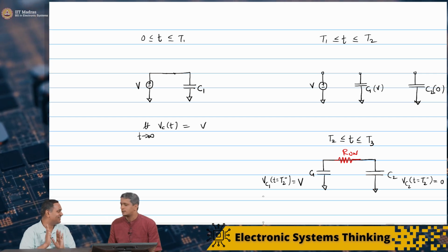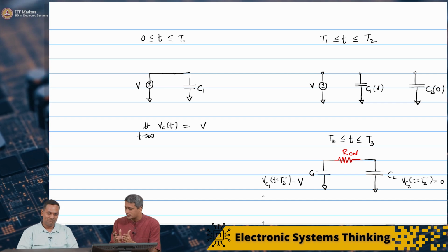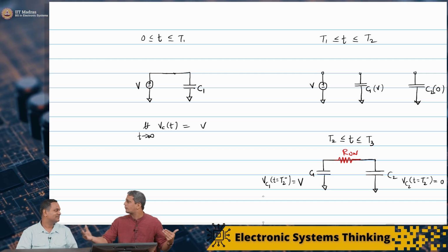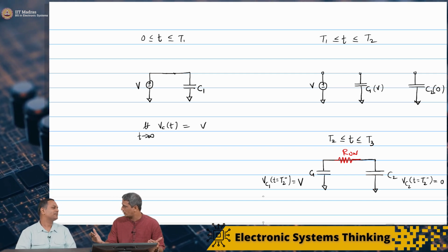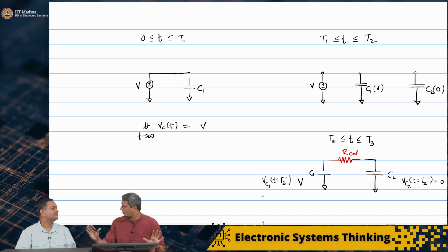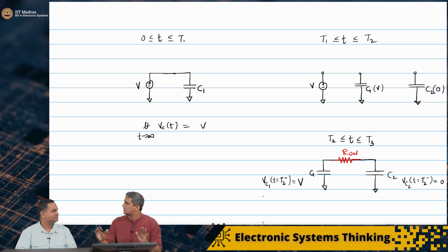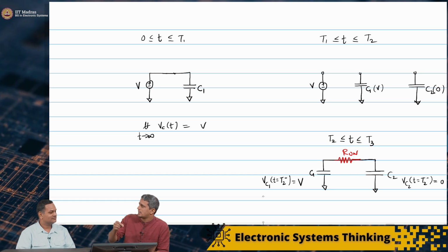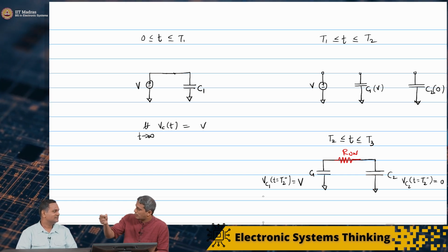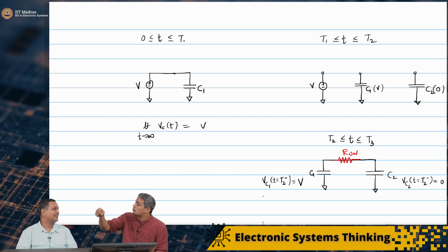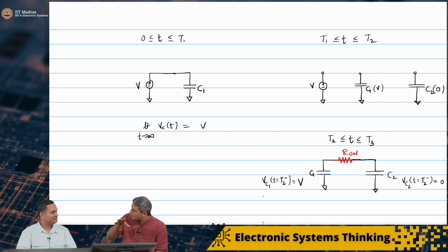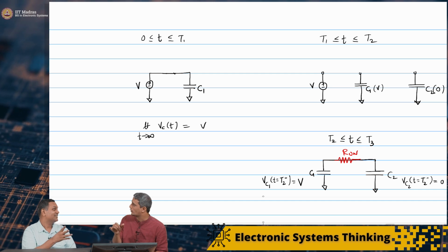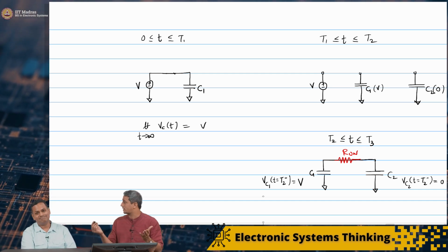It just depends on C and V, not on the resistance. The resistance only determines the time it takes, because we are giving it enough time and looking at steady state values. Eventually they will all come to the same voltage, whatever the resistance. Energy lost will be the same, because I squared R is the instantaneous power, and energy is power integrated over time. The current may be slow over a longer time, or fast over a shorter time, and therefore the energy lost is still the same.